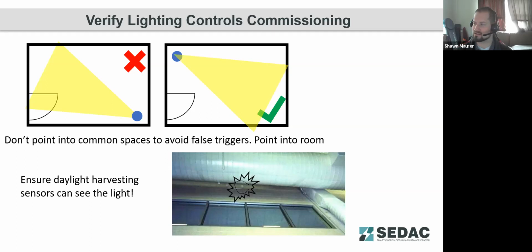They're also going to be checking the sensitivity setting on those sensors, so there's not false triggers just from the air handling system kicking on. I've seen ultrasonic sensors set too close to supply grills that then trip just from the vibration change in the airflow pattern. We also commonly have had that issue with passive infrared sensors, where in classrooms or other spaces that may have hanging decorations from the ceiling, those airflow patterns can then create a false trigger on those systems and turn lighting on when no one's in the space.